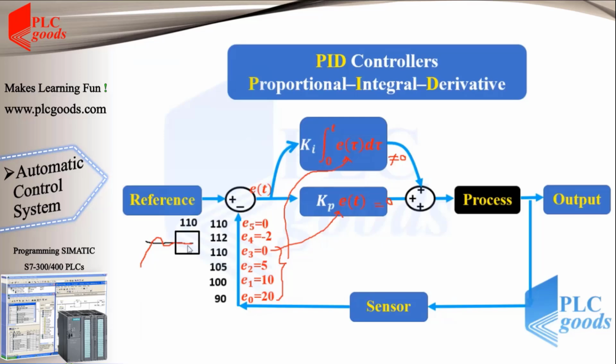Pay attention that at the beginning of the controlling process, when the error values are high and the elapsed time is small, the proportional section plays the main role in determining the output of the controller. But with the passage of time and the reduction of error values, the output of the integrator term plays the main role in determining the output of the PI controller.